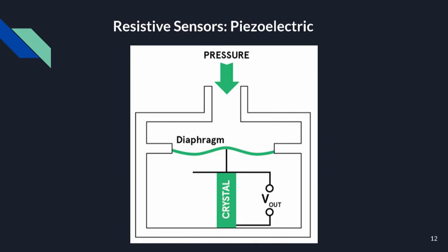Piezoelectric transducers produce an output voltage when a force is applied to them. They can operate in the reverse mode as well, where an applied voltage produces an output force. They are frequently used in ultrasonic transmitters and receivers. They are also used as displacement transducers, particularly as part of devices measuring acceleration, force, and pressure.